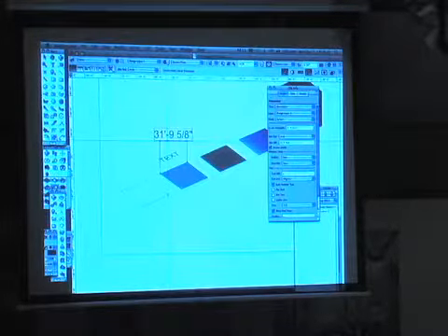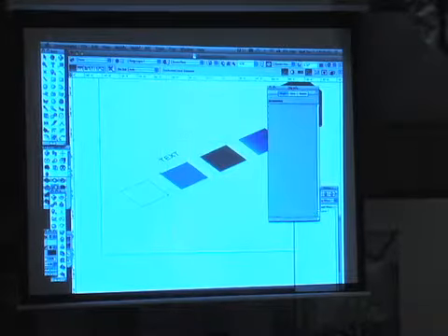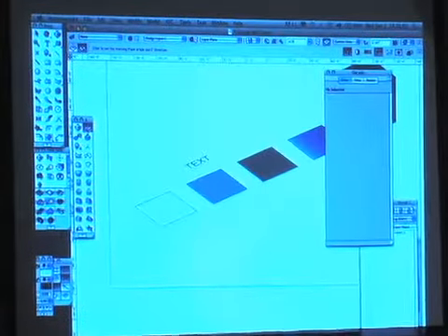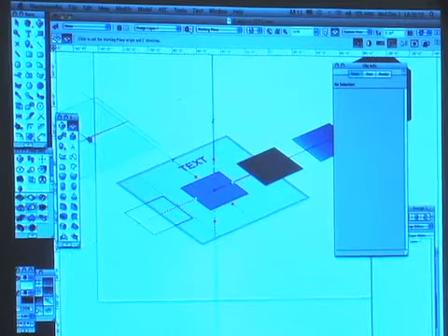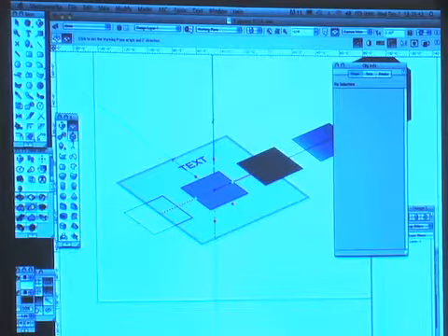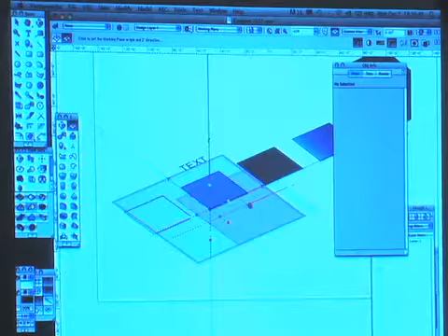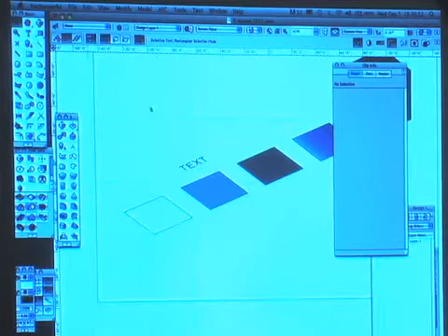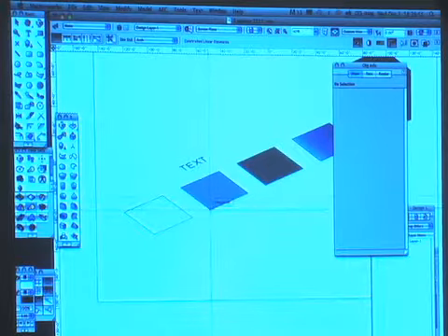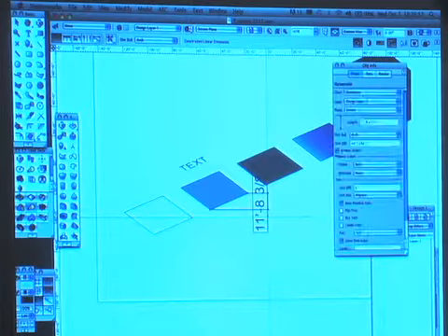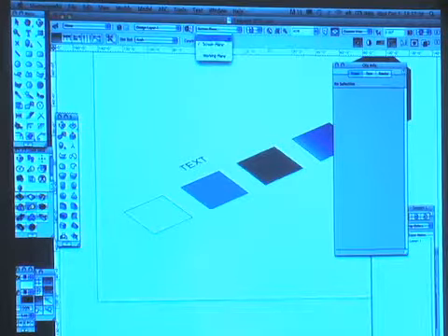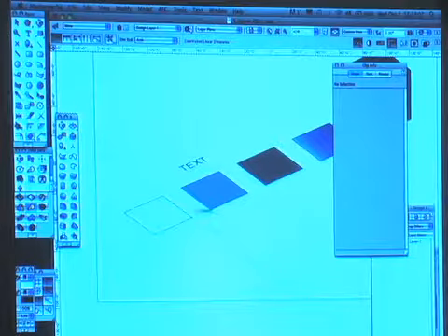Again, I need to reset my orientation here. You have to set your working plane. Working planes are much more important in this version. You use the working plane and set it to the design layer, and now I can begin to, leave that set. Use my dimension. Why didn't that orient the right way? You have to adjust to where it says on the top there, screen plane to layer plane. There, yeah. Yes, that's probably my problem. Thank you, Paul.